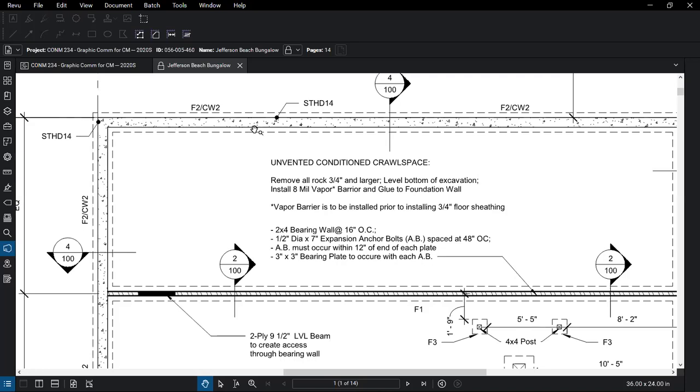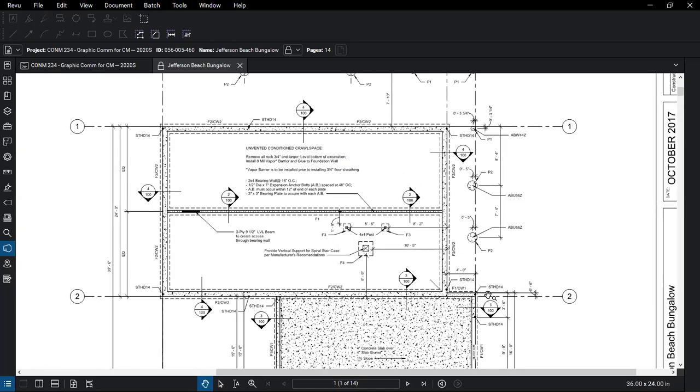And for one reason or another, traditionally when drawing plans, the foundation wall would be put in first. And then if you look at the hidden lines on each side, that represents the footing in this T foundation system. And that would be drawn in after the fact. So in terms of us modeling, we're going to model it in that same sequence. We're going to add the CW2 walls in first, and then we'll come in and add the CW1 walls in. And then in a different video, we'll talk about how to place the different footings.